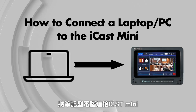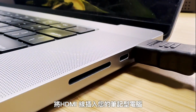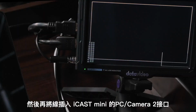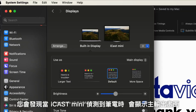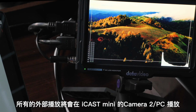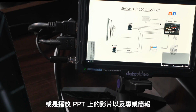To connect a laptop to the iCAST Mini, you will need to use an HDMI cable. Turn on your iCAST Mini, and when it's finished booting up, plug the HDMI cable into your laptop. Then connect the HDMI cable into the PC/Camera 2 port on the iCAST Mini. You may notice the iCAST Mini program output flashing as it detects the laptop, and your laptop will recognize the iCAST Mini as an external display. Anything you have in the external display will play on the Camera 2/PC source of the iCAST Mini, including mirroring your desktop or playing slides or videos from a PowerPoint or ProPresenter presentation.